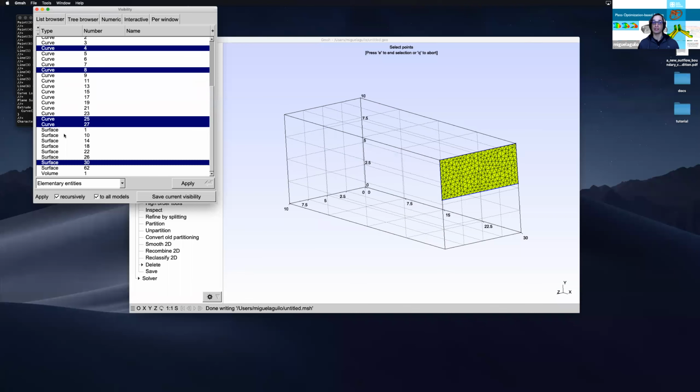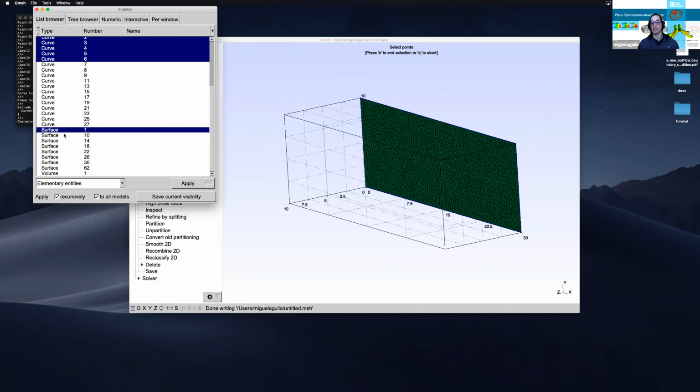But in the future, if you find yourself working on your own and doing the translation yourself with our tools, then you can use the Gmsh visibility tool and the awareness that the way Plato names the surfaces is by assigning a name, and the name is surface, and then an ID to that surface, and that ID starts from 0 and goes all the way to the n number of surfaces, in increasing order based on your ID number from Gmsh.